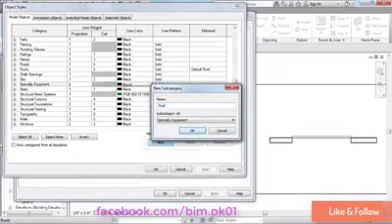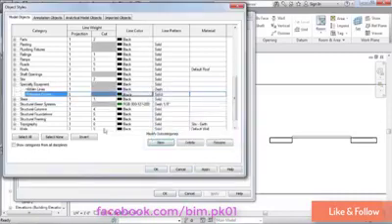For example, earlier in the training series, we began creating our awning family, which we're going to look at further in later chapters. That would be under protective covers in the master spec. So if I'm the manufacturer for that piece of equipment, I might want to create that subcategory. I just simply click OK there. And now I have that subcategory.